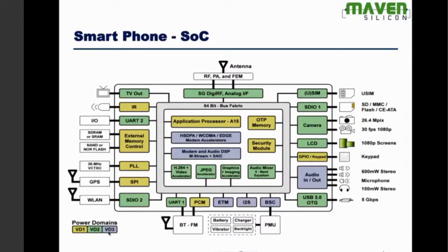It's obvious that the entire chip is not going to operate at a constant voltage level. Different blocks will operate at different voltage levels. This is how we try to reduce the power consumption. When doing this, we look at the activity of the block. If the IP is going to be a high performance device, then we define the voltage level accordingly. If the IP is going to be a low performance device, then we try to reduce the voltage level. This is how we reduce the power consumption.